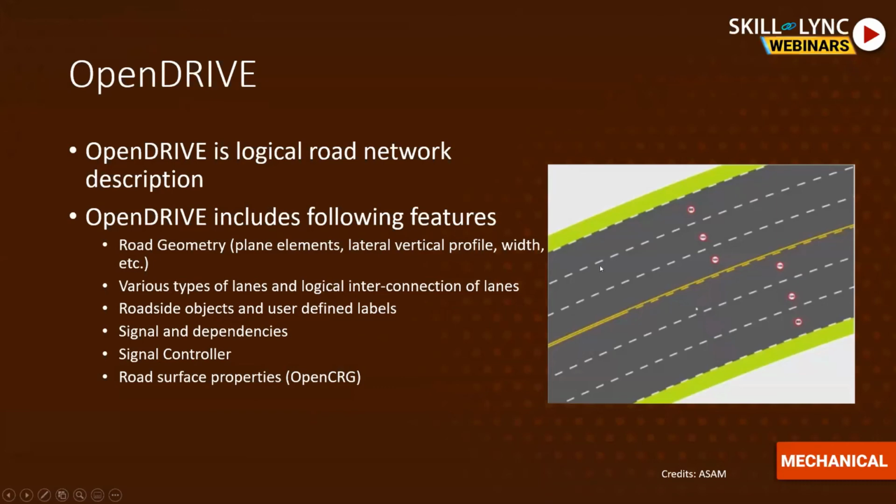So there are road conditions, you have to model the road condition: what is the length of the road, what is the width of the road, does it have a footpath on it, what is the speed limit of the road. These aspects of the road are important. And not only that, even modeling the surface of the road, in terms of getting the vibrations from the brake or the suspension system. So for designing the suspension system, the road surface is also important.